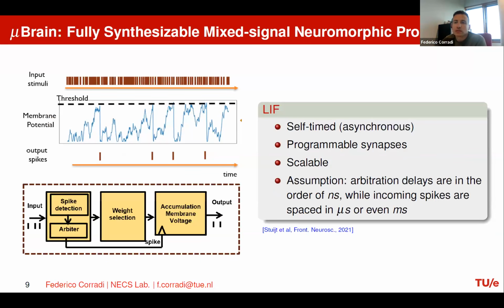or you can imagine that you can now change the accumulation of the membrane potential. Instead of having it in a digital accumulator, you can make it on a membrane capacitor, right? It's like in analog, and then you can use the current that discharges the capacitor with a certain time constant, and then you will get a leakage. Of course, this is a different design, but everything is possible.